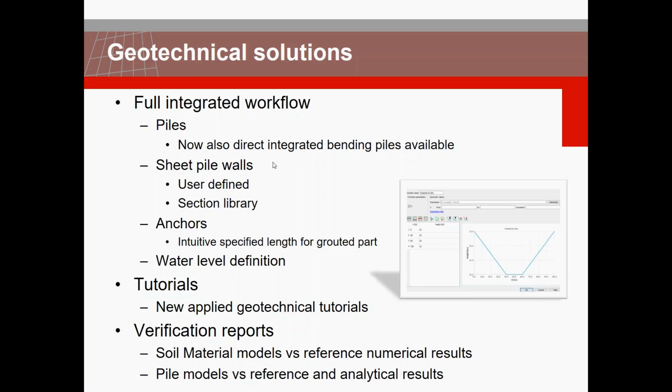For sheet pile wall, we have different references for our profiles. These profiles can be addressed from the existing profile library that we have in the installation in DYNA, or you can define your own profile as a user. We have a couple of slides I touch base on, and then Jean-Claude is going to give a detailed live demo. For anchor, there is a very nice and integrated solution in terms of introducing the grouted part, the bond slip behavior, the anchorage length, and all those things are defined in one fully integrated environment.